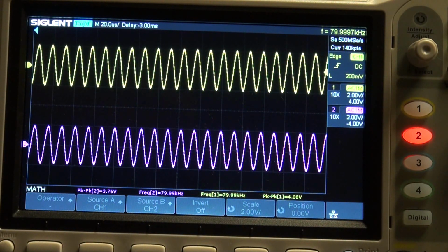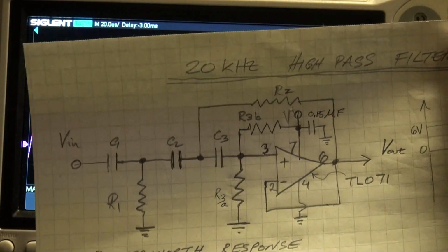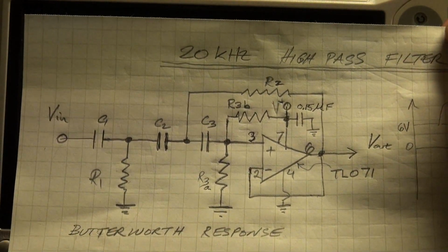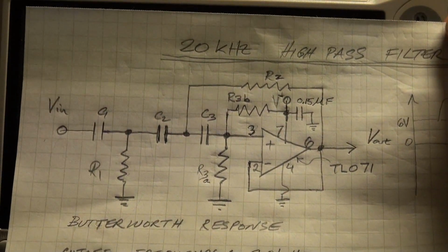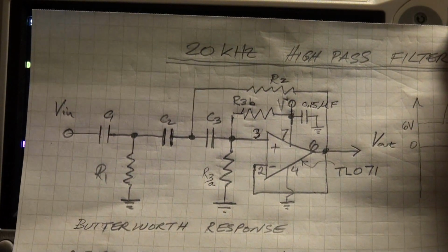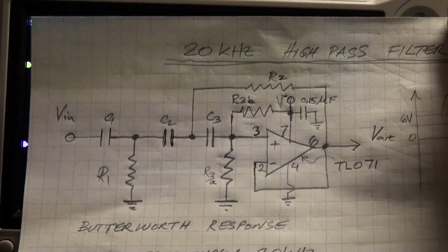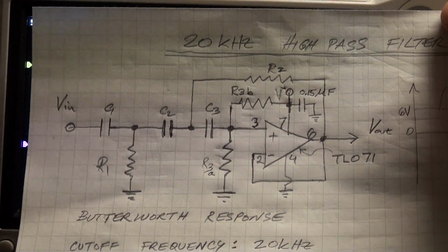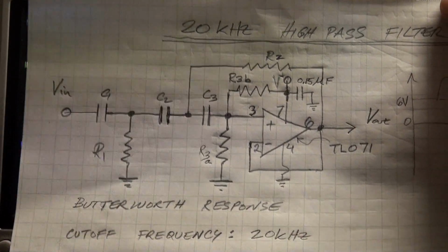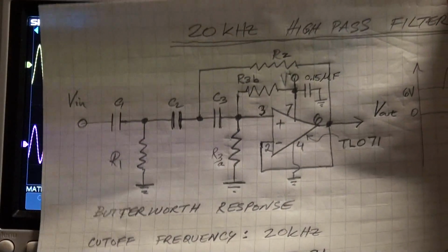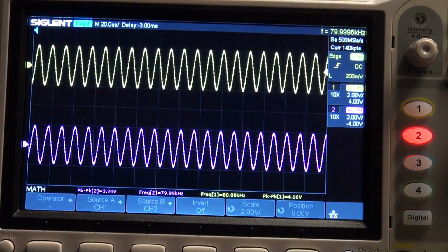And I'm suspecting that the capacitors that I'm using, the C1, C2, and C3 that were given by the filter design tool on the website, here they are, in fact have some effective series resistance that we'll check in a little while. See, these are ceramic caps, and they're not the best for signal processing applications. Should be using metal film capacitors, which I'll probably end up changing as soon as I get a hold of them, but at the moment the ceramics is what I had.